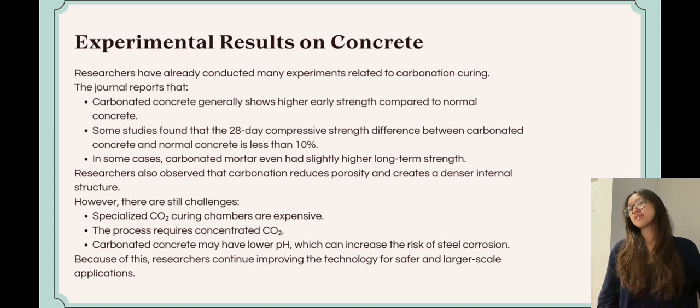However, there are still challenges. The first is that specialized carbon dioxide curing chambers are expensive. And then the process requires concentrated carbon dioxide. And carbonated concrete may have lower pH, which can increase the risk of steel corrosion. Because of this, researchers continue improving the technology for safer and larger scale application.